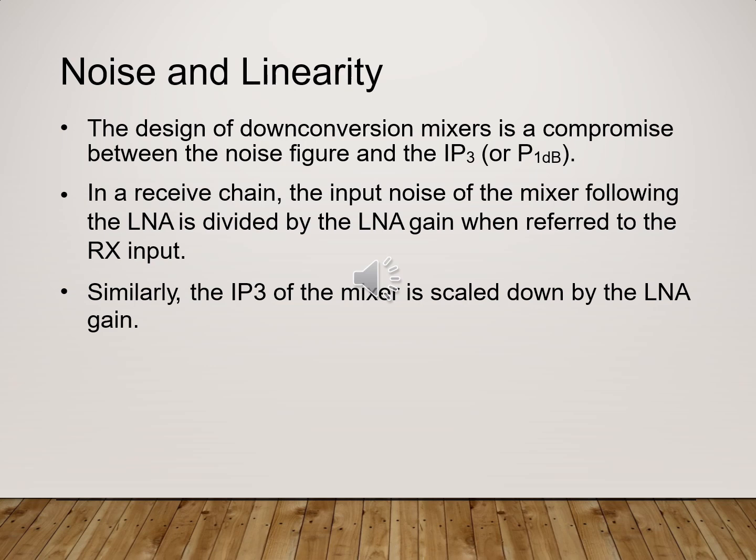In a receiver chain, the input noise of the mixer following the LNA is divided by the LNA gain. So we need the gain of the LNA to be high. Similarly, the linearity, or the IIP3, of the mixer is scaled down by the LNA gain.